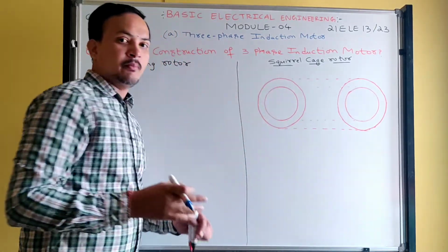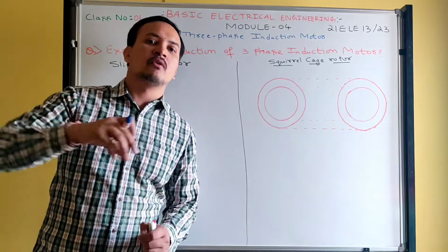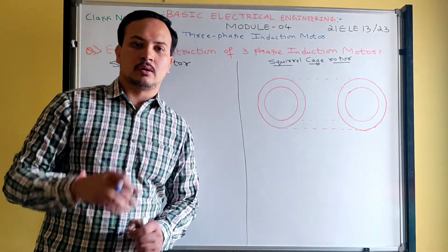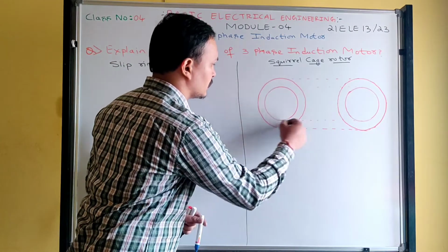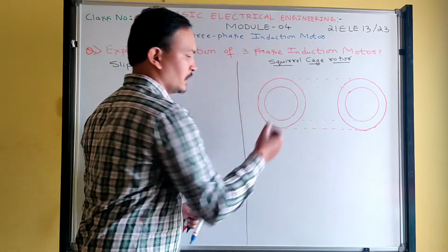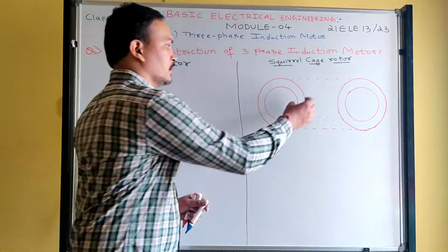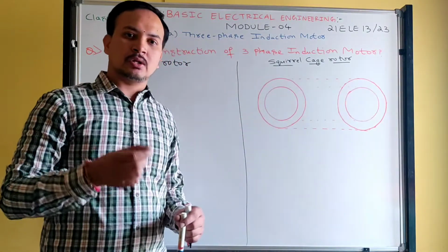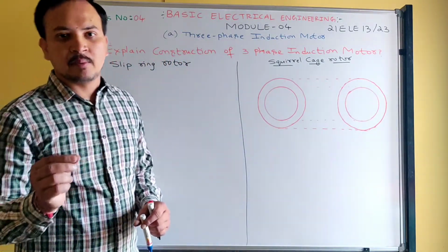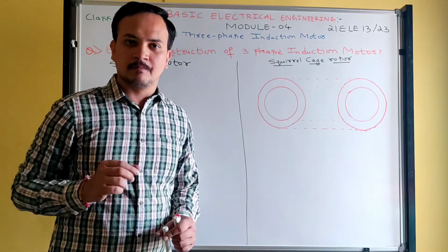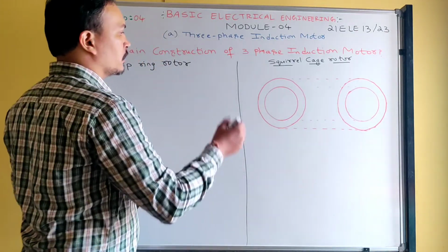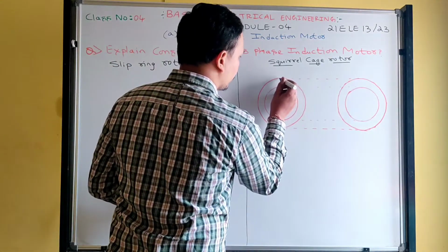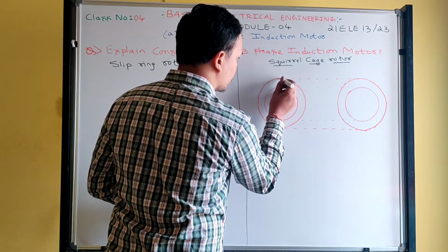They are going to make a fixed number of holes on the rotor. See, this is also called rotor lamination. It is one plate. Okay, this is a plate or lamination. The thickness of the rotor plate is again 0.25 mm to 0.5 mm. But in that plate, they are going to make holes. Okay, so let me draw some holes here.